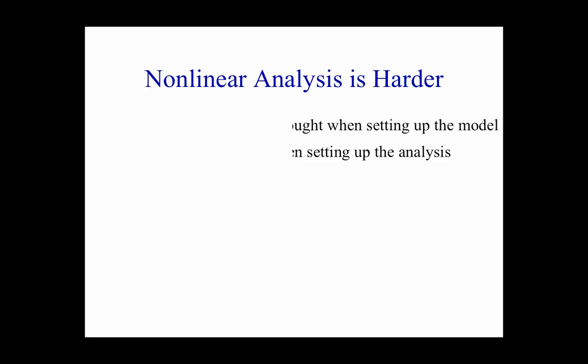How we model has a great impact on what the results are going to be. I could show you blind prediction contests on single columns, where people just picked slightly different input parameters, and the results varied quite widely. So it's really important when you're creating your nonlinear model to think about these things. Typically, students starting off are just going to see two beam columns and connect them. There's a lot more thought you have to do. Desmond's going to talk a little bit about it tomorrow.